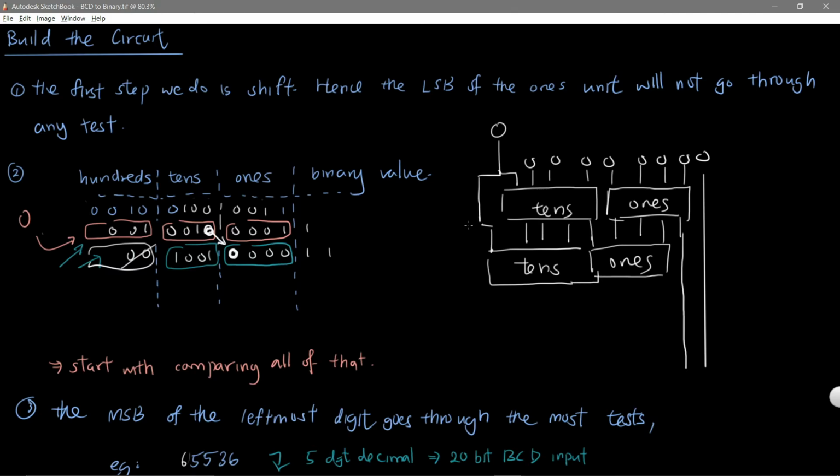Alright, so depending on your case, let's say you have built to the third level, and this one here is straight to the bottom. 1, 2, 3, 1, 2, 3, 4. And if you put a chip here, it is going to have 1, 2, 3 and another logic level 0 here, right? But what happens here is that, you see, these original values here, when they reach here, it's only 2 places. So when it's only 2 places here, you don't actually need this anymore. So you can just go ahead and not put this chip, for efficiency and for overall circuit power consumption if you're actually building a circuit out of it.